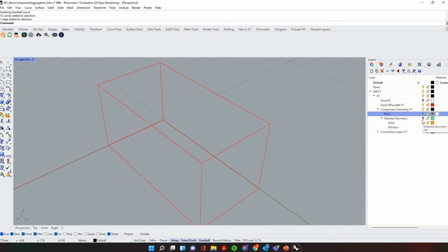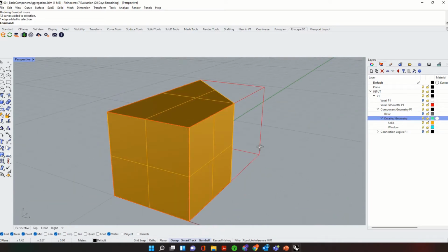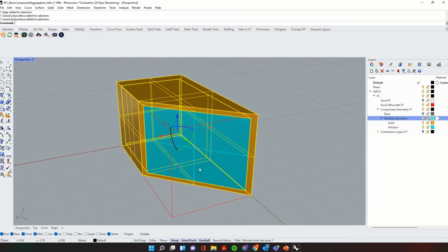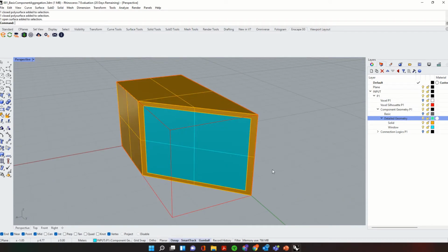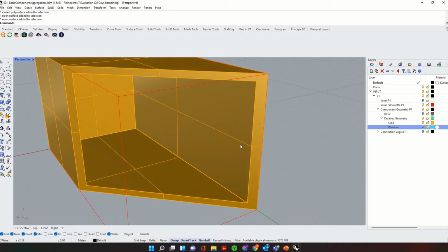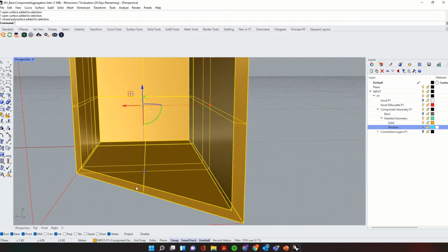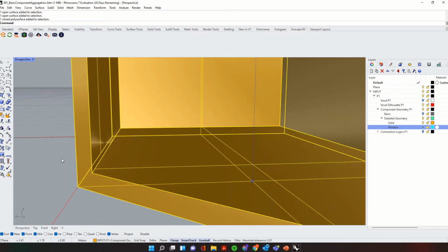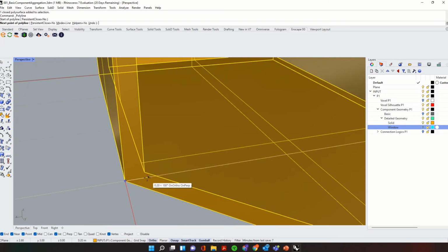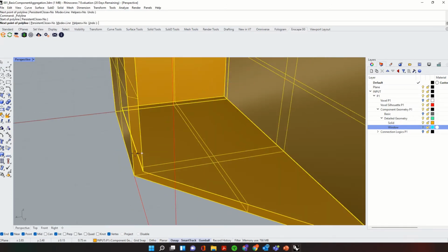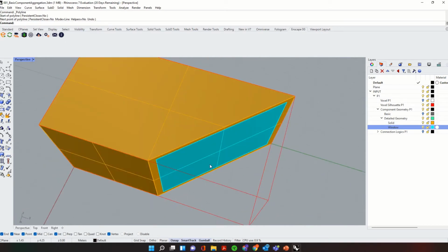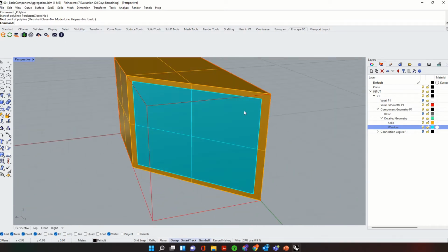And then what I'm also doing under detailed geometry is I'm just very simply delineating between what is solid and what is clear. So I've given this voxel shell, component shell, a bit of a thickness. I'm just using 150 mil thickness roughly, and then a glazing opening for now.